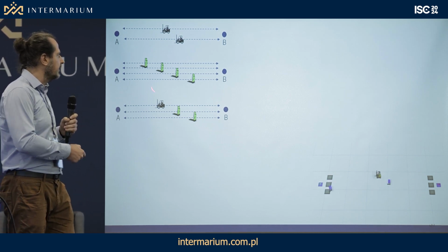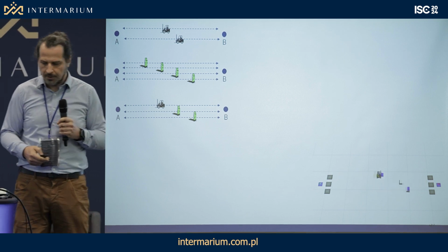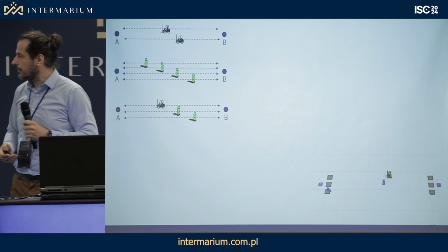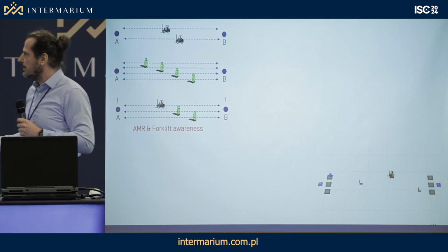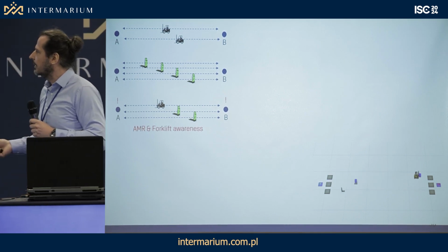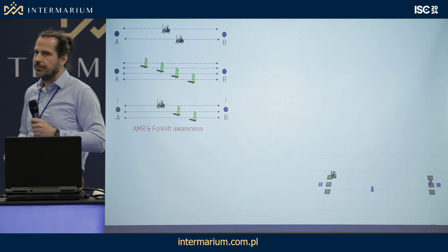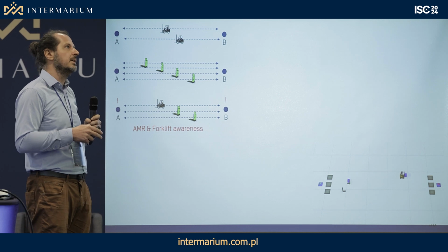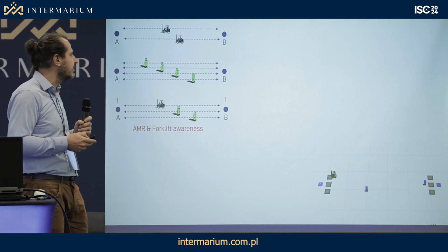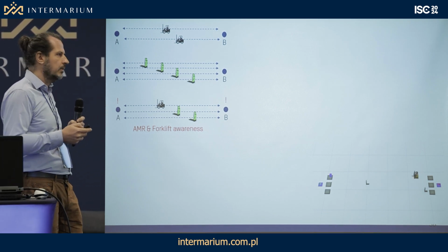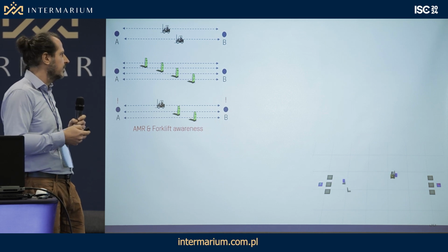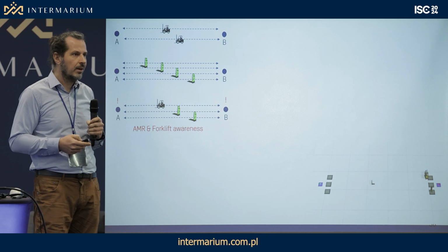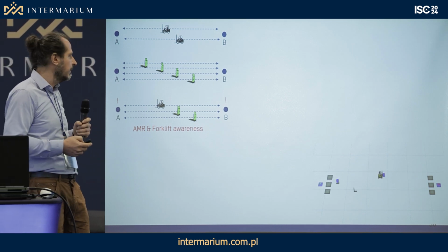But this is often happening in projects. We see it often, but it needs some kind of attention, because if the mobile robots meet forklifts in the points of picking the pallets, there is always, or maybe in 80% of the time, there are problems. We don't like each other. They will block each other. There is a risk of collision. So those points should be somehow separated or treated with special attention.